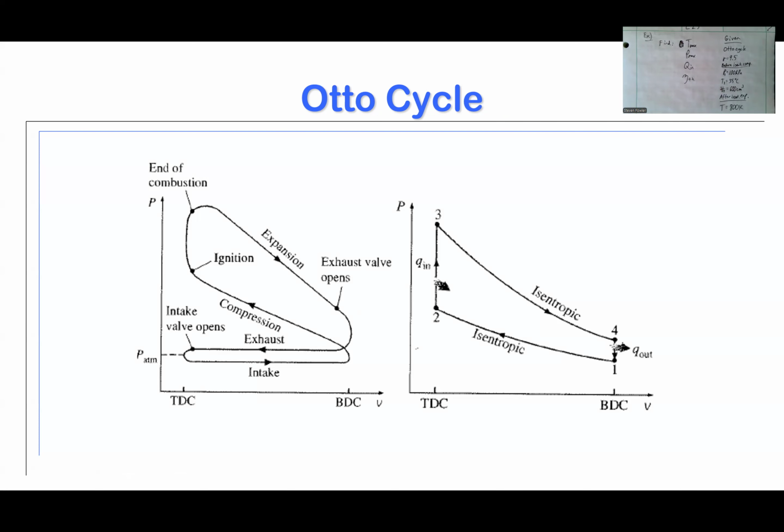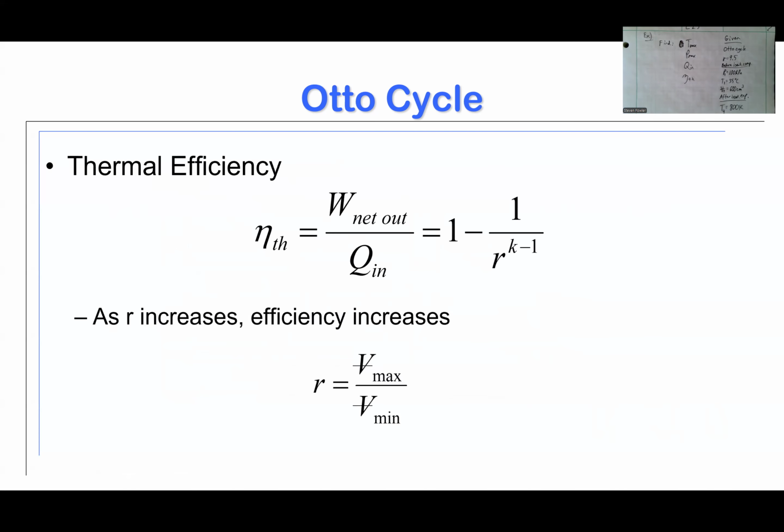And then after the isentropic expansion, that goes from 3 to 4, where I'm going from a small volume out to a large volume. After that process, that is state 4. So I'm going to label that temperature there as T4. So it's important we know what the problem statement is telling us.